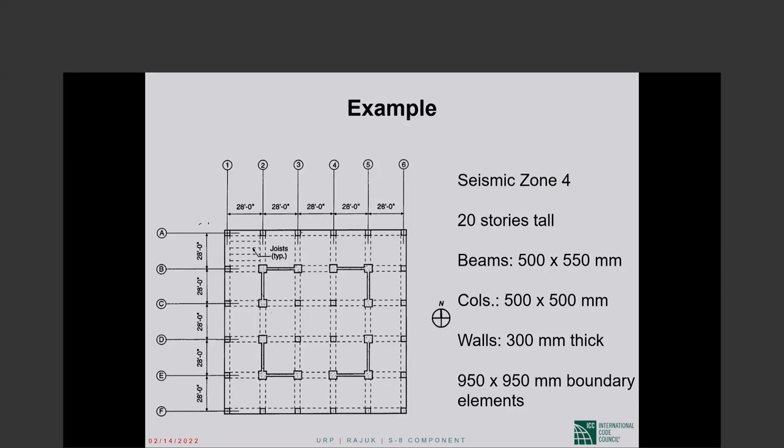So can we use coupling beams in a building frame system to connect two separate shear walls? It has nothing to do with the building frame system. The coupled shear wall will be treated as a shear wall. Building frame system would mean that you have 100% gravity force resisting moment frames to go together with this coupled shear wall that will have to resist 100% of the lateral forces.